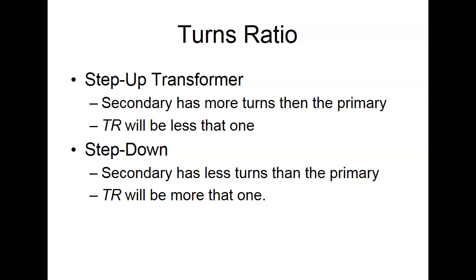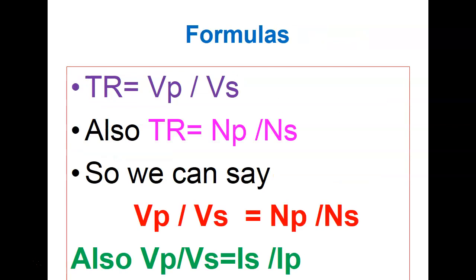And like I said, industrial transformers, they don't rate them as secondary and primary. You have a high side and you have a low side. And you can wire it to do what? Step up or step down. And how do we identify the low side? Those terminals are going to be labeled with what? X. High sides are going to be labeled with H's. And these are all the same thing.